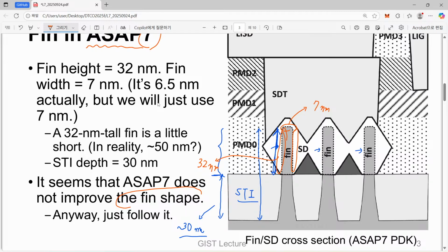What is the reality? So yes, in reality, in TSMC, Intel, at the 7 nanometer node, the actual height seems to be, because usually these days they do not expose or disclose the actual value of their fin shape, so we have to estimate the dimensions by TEM image inspection. However, it is known that its height at 7 nanometer technology would be around 50 nanometer.